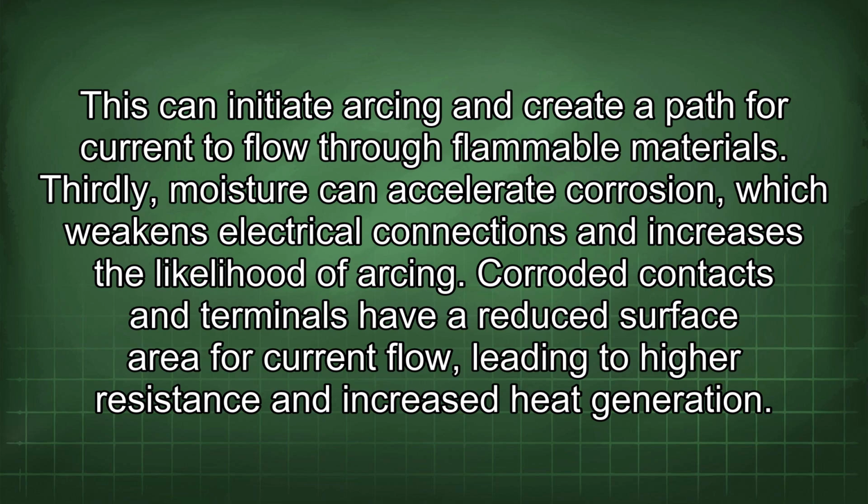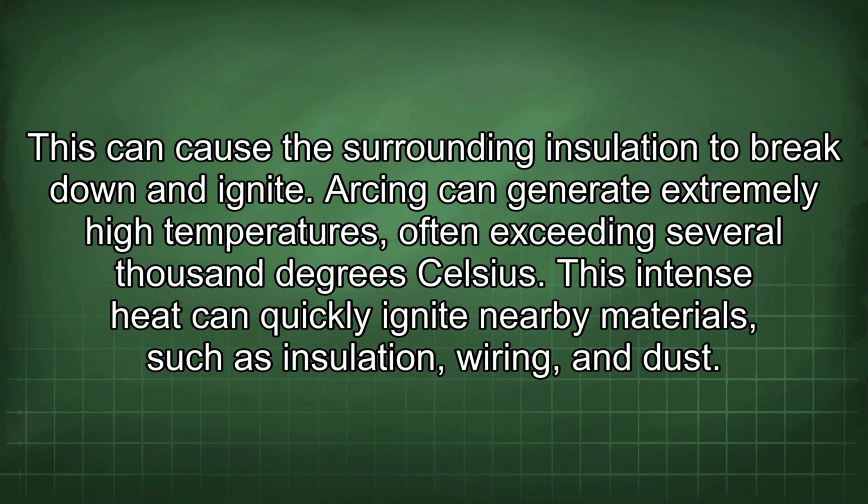Thirdly, moisture can accelerate corrosion, which weakens electrical connections and increases the likelihood of arcing. Corroded contacts and terminals have a reduced surface area for current flow, leading to higher resistance and increased heat generation. This can cause the surrounding insulation to break down and ignite.